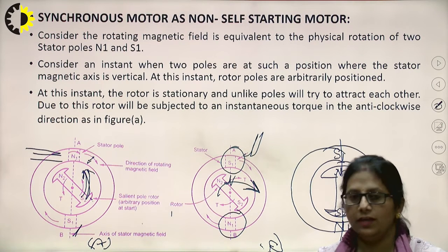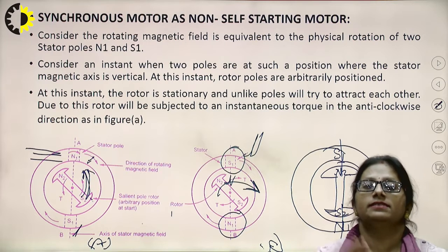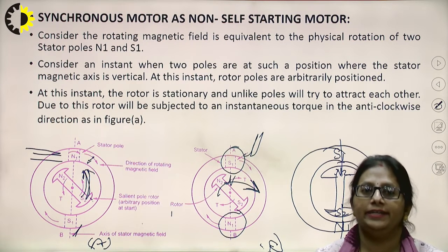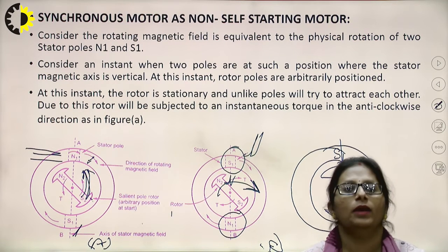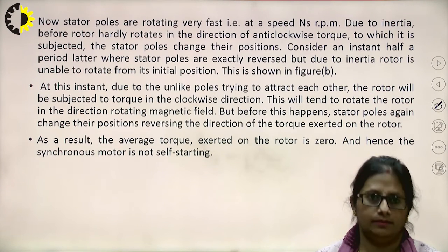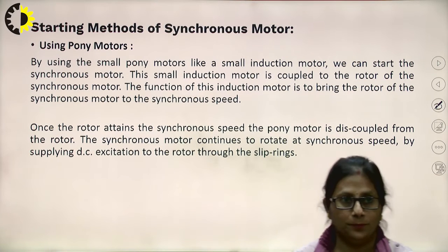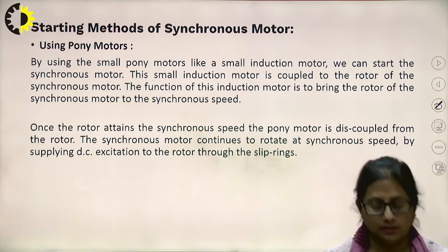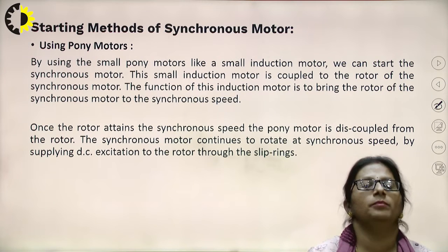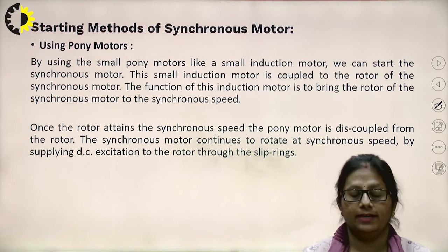So all the three cases fail. That's why a three-phase synchronous motor is not at all a self-starting motor. Okay, so how to get it started? Right? How to get that starting torque? There are various methods by which we can make the synchronous motor self-starting.